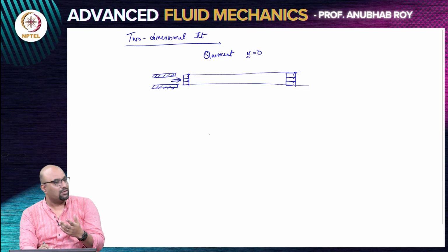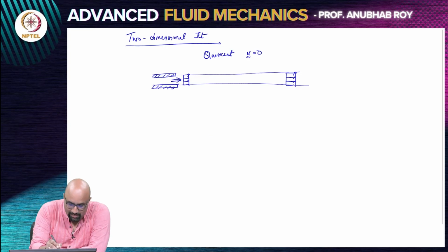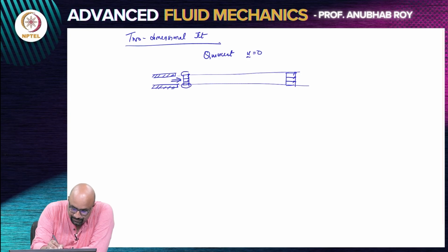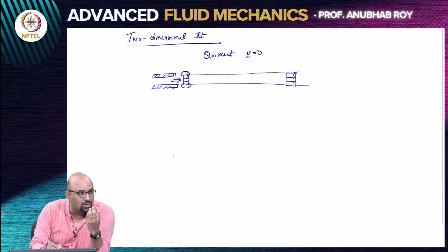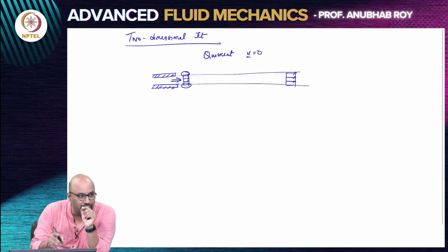And now you see what we are going towards. When we have viscous effects, howsoever small viscous effects there may be, there is this region where the jet is coming and meeting the quiescent fluid outside. So, when you are blowing out wind, the wind that is coming out from your mouth is meeting the quiescent air that is around. It is trying to make its way through, but at the interface between the two fluids, there is a high speed fluid that is meeting a neighbor who is almost quiescent.